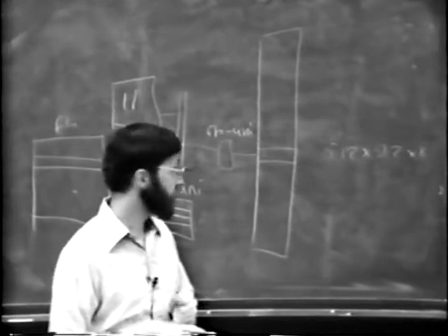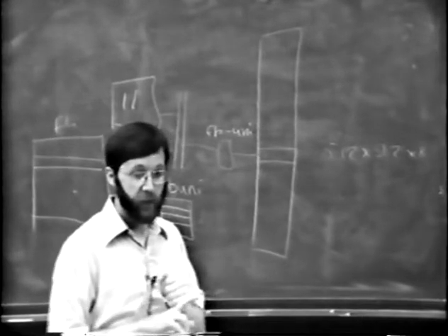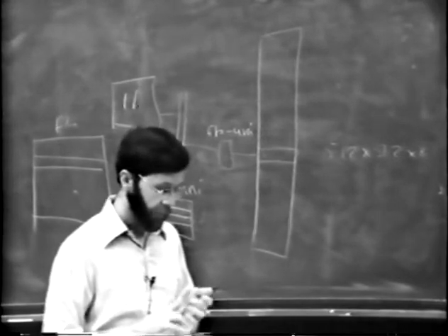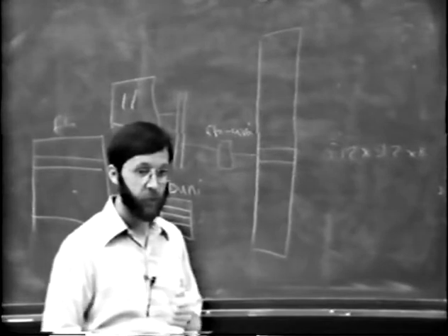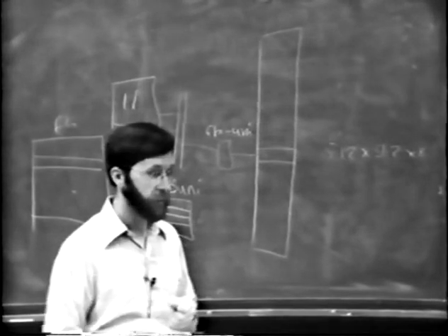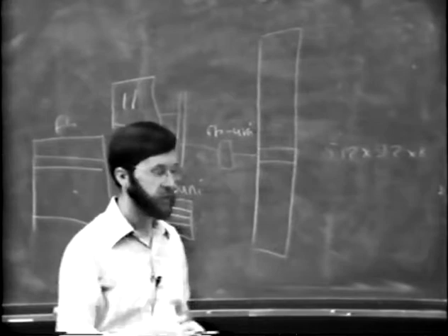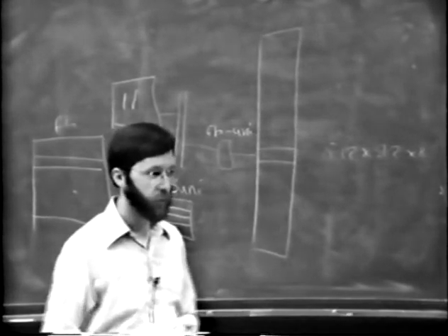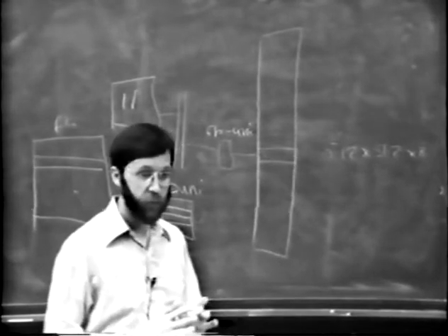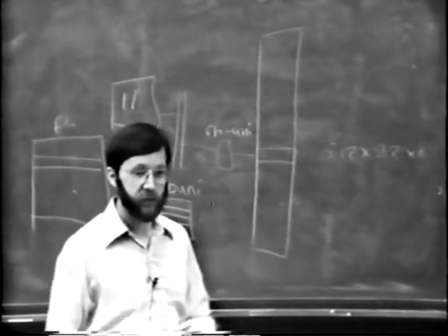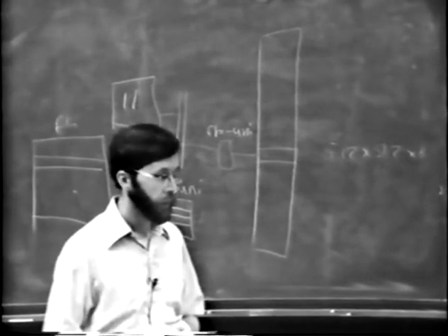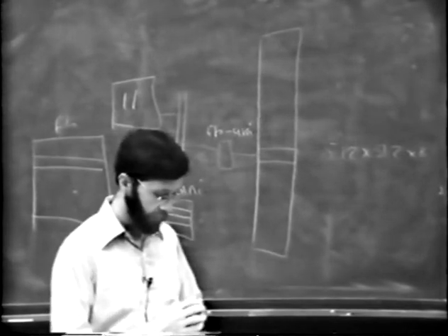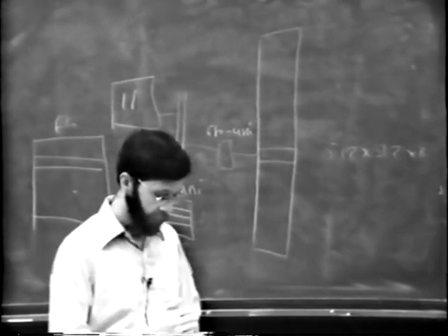That's one notion. The other notion is that frame buffers ought to be built with bit planes. But for many who are building bit planes, those bit planes are visible to the user. So if you write 16 bits, they're written in funny locations in the memory. And their way of making it so that it's easy for the user is to put in a little microcomputer inside the frame buffer to straighten out all the bits for you so things happen in the right way. And each of the people who have these various opinions would then discuss with us, because we're a fairly visible place, about the right way to do it.